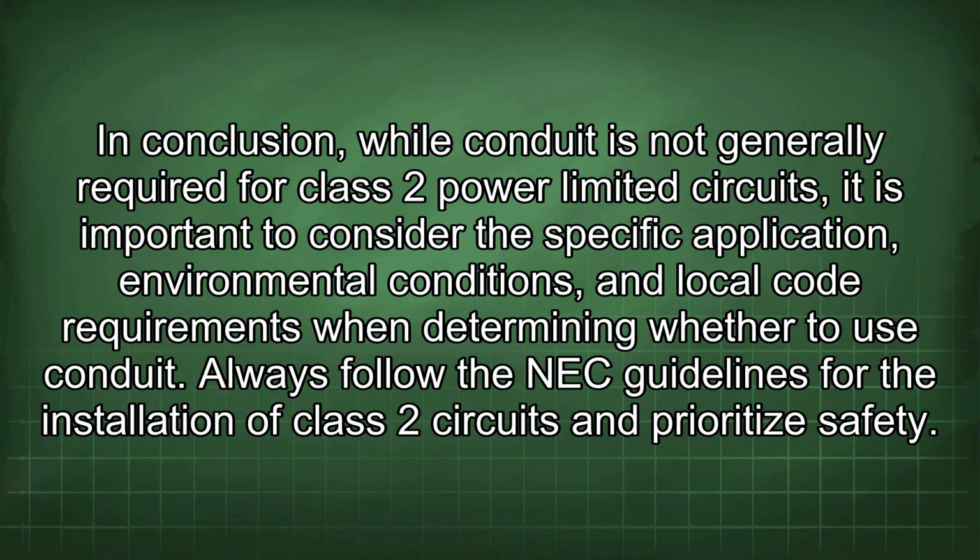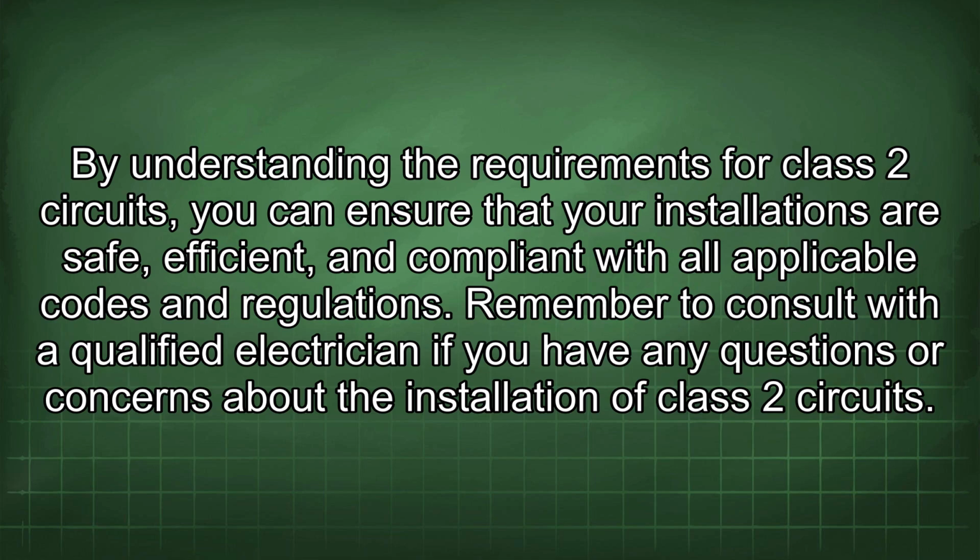In conclusion, while conduit is not generally required for Class 2 power-limited circuits, it is important to consider the specific application, environmental conditions, and local code requirements when determining whether to use conduit. Always follow the NEC guidelines for the installation of Class 2 circuits and prioritize safety. By understanding the requirements for Class 2 circuits, you can ensure that your installations are safe, efficient, and compliant with all applicable codes and regulations.